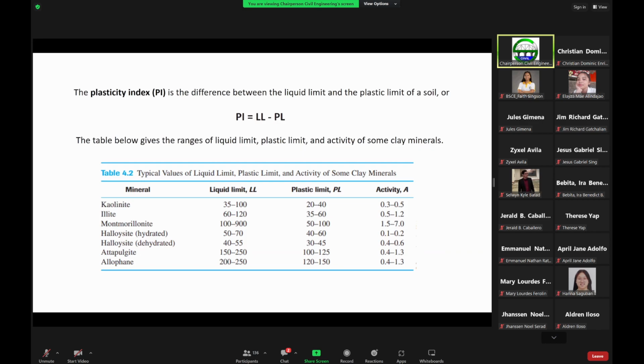I just attended a meeting earlier this afternoon where we were discussing a project whose site is a bit liquefiable, and we were trying to design for a power plant somewhere here in Luzon. Based on my assessment, the site is liquefiable, so we are now discussing whether to do ground improvement works, such as stone columns, or bored piles, or deep foundations.